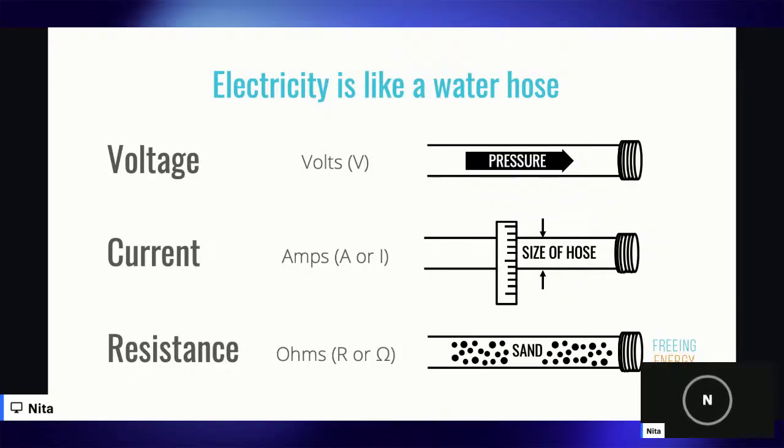During your inspection, you're going to look to verify that the correct voltage is being supplied to every device, that your circuit breakers and wiring match the voltage requirement. The voltage rating on the device has to match the voltage that's coming from the circuit. Otherwise, if it's too little, it won't work, or if it's too much, you'll create a hazard.